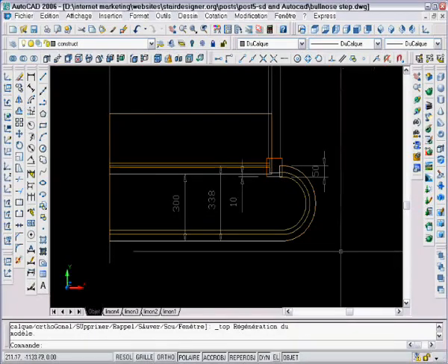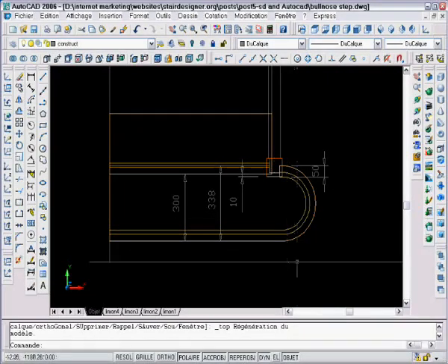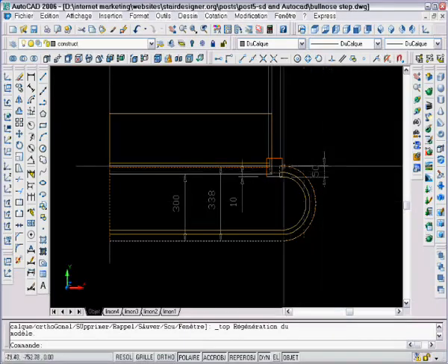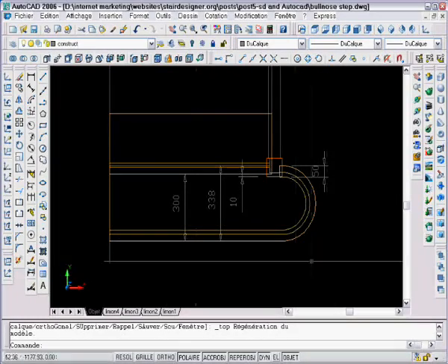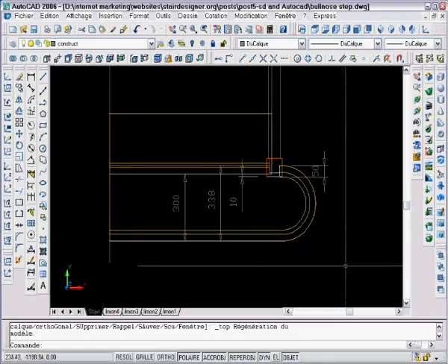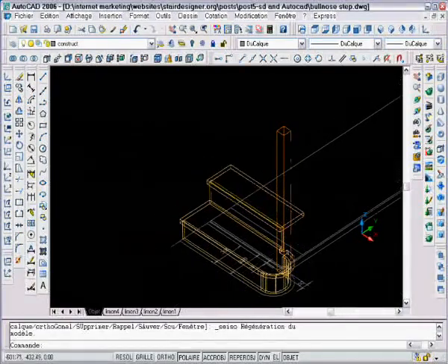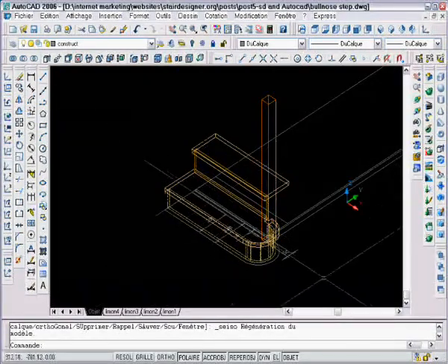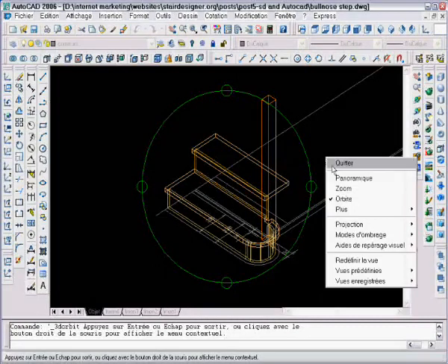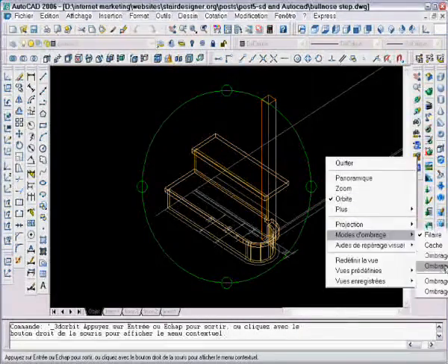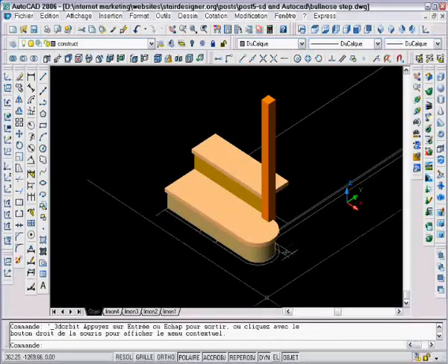Now, in general, I like to make the first step a little bit wider than the other steps, and I like to put a curved riser, and the bullnose assembles on the exterior side of the newel post in a specific way. So if I show you, this is the actual plan which I draw up in AutoCAD. Here is the actual starting step with the first and the second risers, just to give you an idea of how I like to build this. So if I show you with some 3D, it gives this sort of effect.